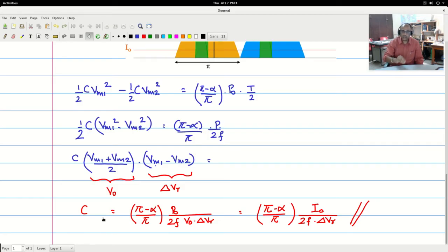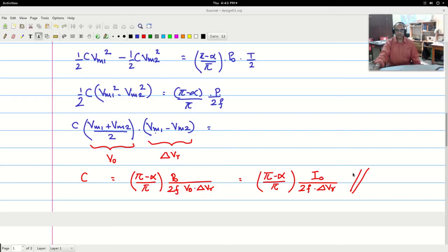So normally what is done in practice is, once you calculate, let us say you get some 15 microfarads or 10 microfarads, you will take 3 times that value, so 30 microfarads, and put that value. So that even if the capacitor that you have bought is minus 40% down, it will be able to handle these kinds of variations. So this is how you calculate the value of C.